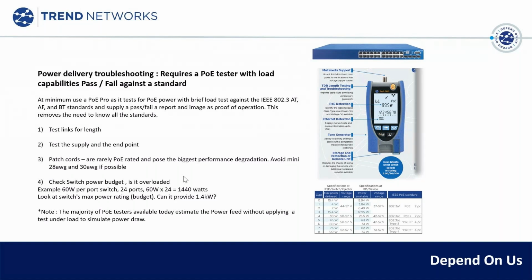So it tests the links for length over the power. It tests the power supply, tests at the power supply and at the endpoint. And this is where it's also capable of at least testing the patch cords. The biggest issue is the patch cords. A lot of the products are typically not PoE rated out there, and it makes sense.